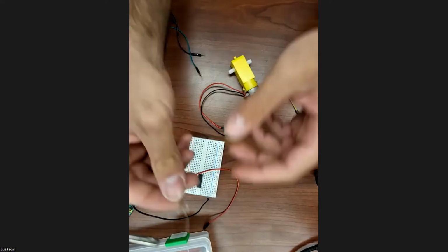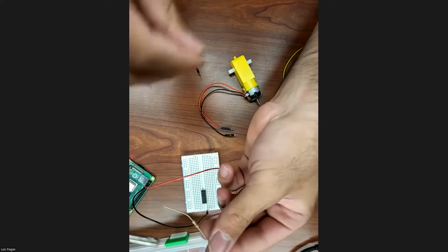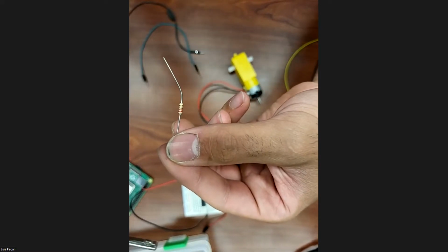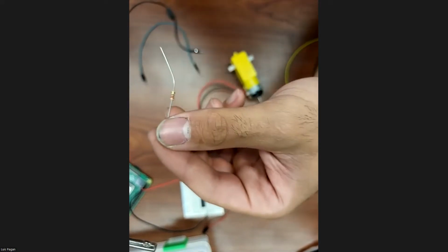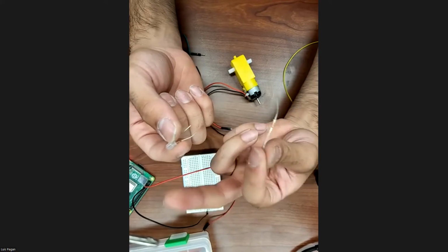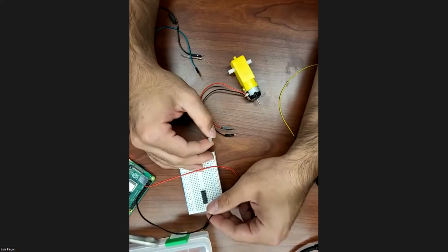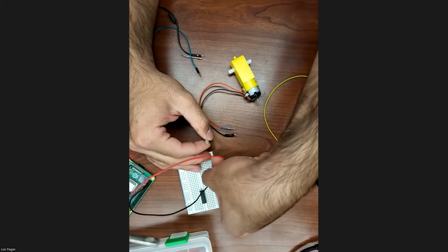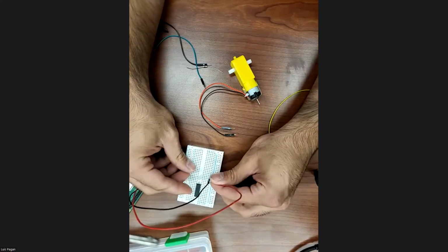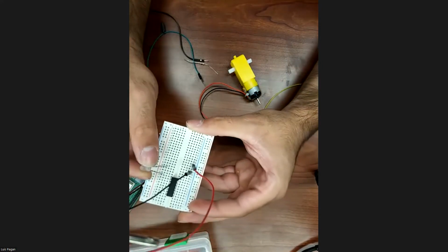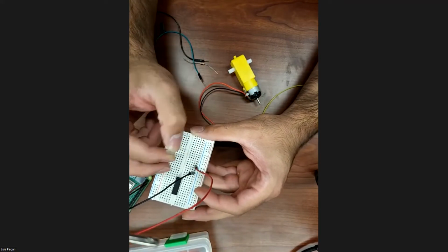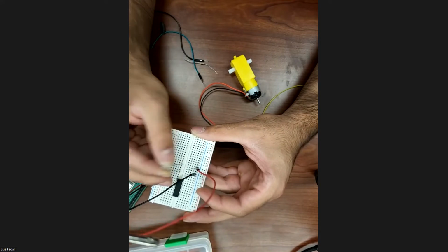So yeah, this is a resistor and an LED. This is the resistor you'll be using for controlling the LED, again just making sure that the current in the LED is not too great to the point where it'll damage the LED. LED is a light emitting diode, so current will only flow in one direction. So let's plug this in really quickly. There's going to be a longer lead on the LED. You want to make sure that's going to the positive side and the shorter one to the negative.